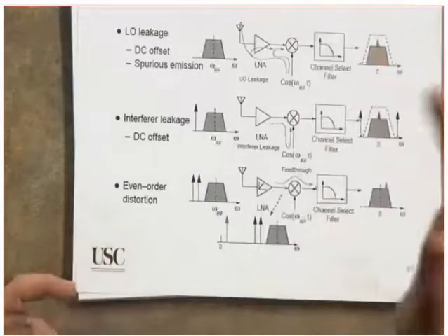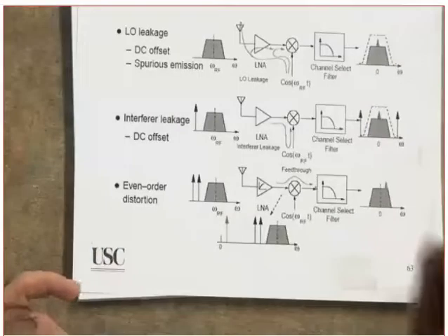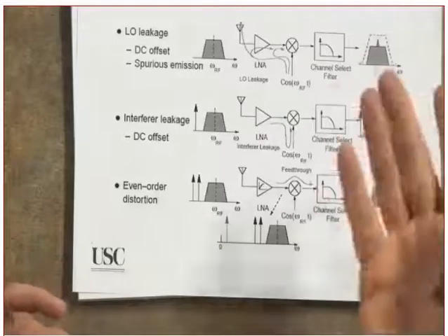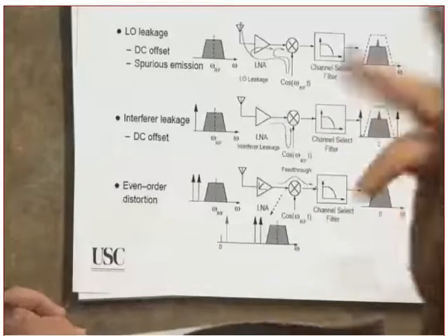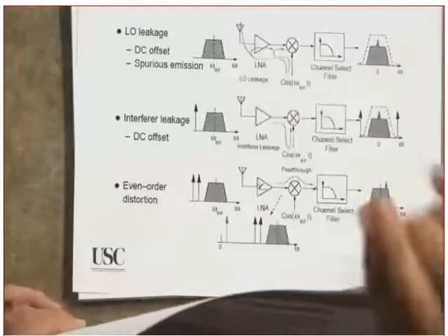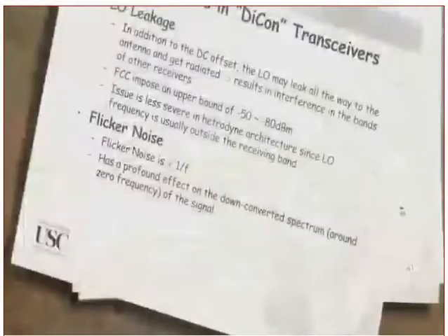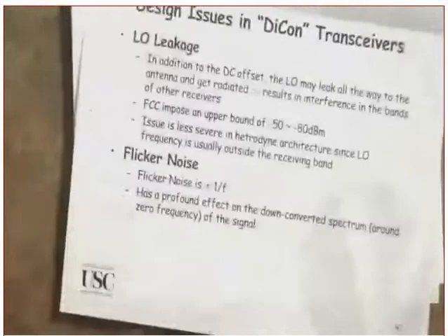Yes? One possibility to overcome this is to use a signaling scheme that is not centered around the origin. It is centered a little bit away from the origin. Are you following on that? So that you can design the blocking filter, which is the series capacitor, to remove only the DC. Yes or no? In doing so, let's see some numbers so that you can get the idea.